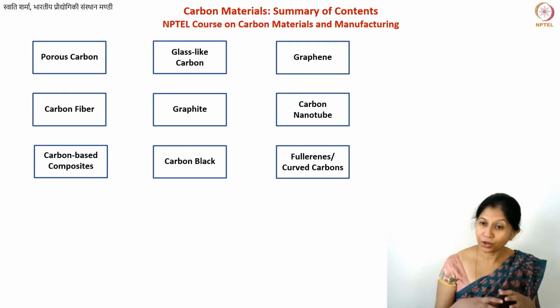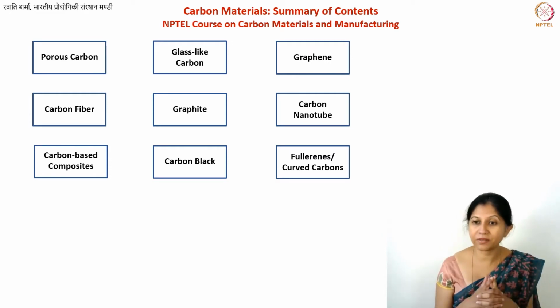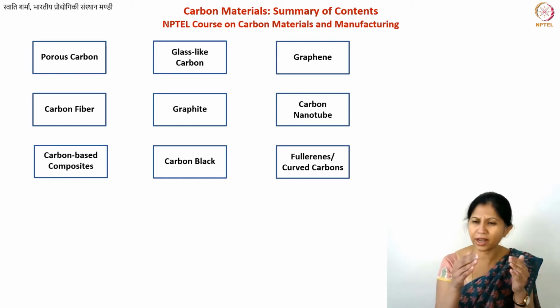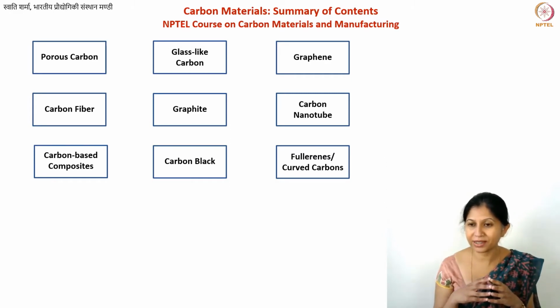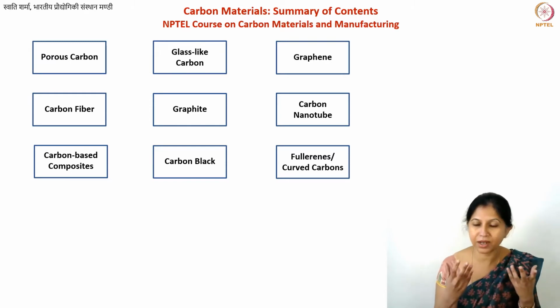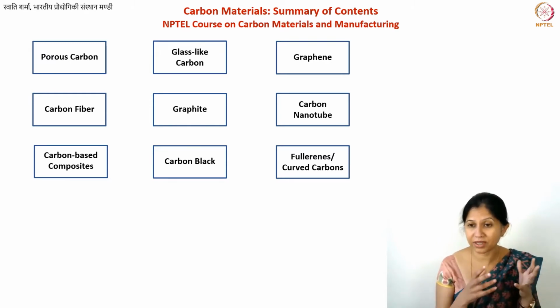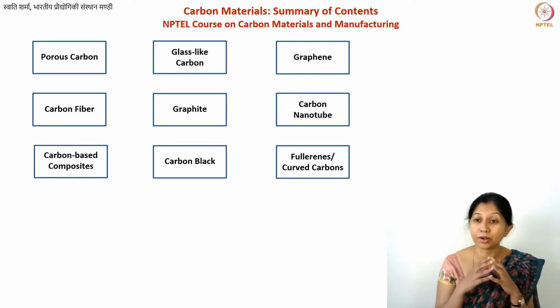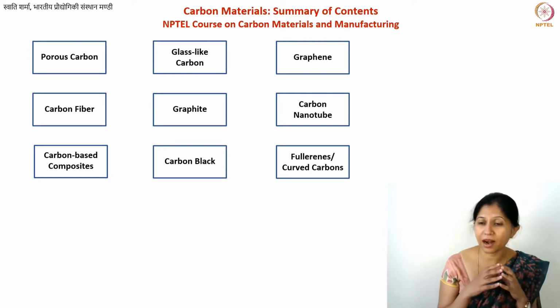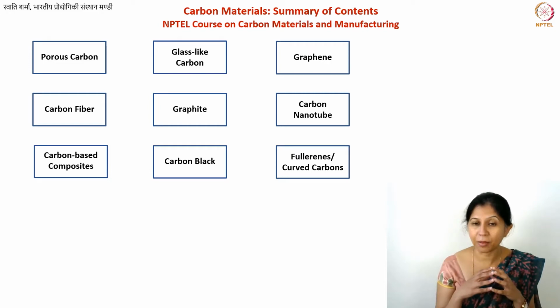So you now understand properly what curved carbon structures are. Any carbon structures which have a strong enough curvature due to the presence of non-six membered rings, we call them curved carbon materials. There are many curved carbon structures that are present in non-graphitizing carbons. For example, porous carbon, also activated carbon, also other char-like carbons, and definitely glass-like carbon.